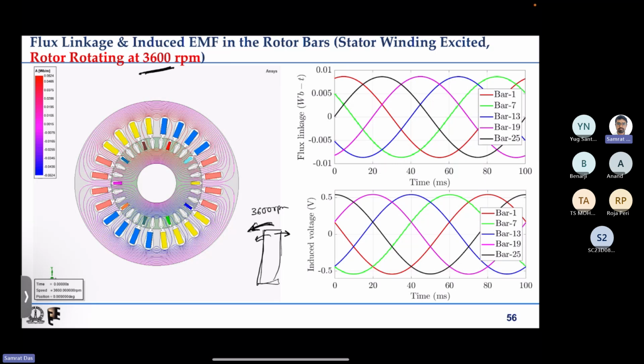So the 600 rpm rotating field with respect to rotor will be in the clockwise direction because the phase sequence is opposite. So with respect to a stationary observer, that magnetic field actually rotates at 3600 minus, because the direction is opposite, minus 600 equal to 3000 rpm.